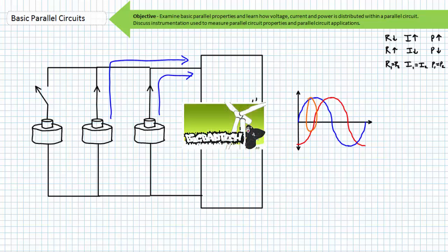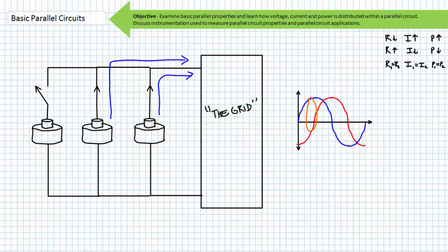Recall from the basic Kirchhoff's voltage law lecture, available at the Big Bad Tech channel, that voltage sources with differing magnitudes in parallel with each other are to be avoided at all costs. Not only will the larger voltage source discharge into the smaller source, such a poorly timed synchronization event will also create a mechanical disturbance in addition to the undesirable electrical events.